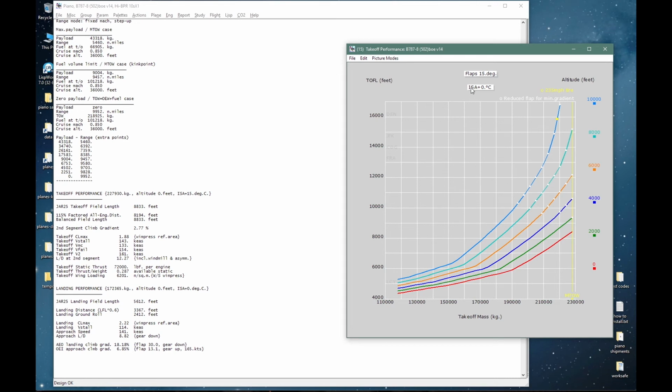Note that there are inherent limitations in field performance calculations. This is a very dynamic phase of the flight. There are significant uncertainties in aerodynamics and ground effect. There is subjectivity in piloting assumptions, so the accuracy levels can't equal those of in-flight performance calculations. In-flight performance is highly accurate. Field calculations are still sufficient for all design assessment purposes, but they are not certification numbers.